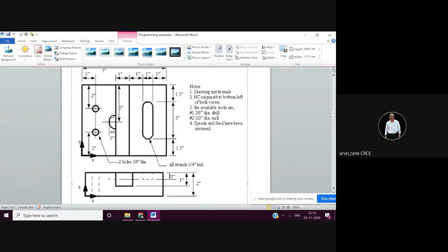So you will have corner, I mean please don't mind, but this is what we have actually seen practically. So here you will have a 1/4 inch radius in the corner, here a 1/4 inch radius in the corner, and in the middle you will get a straight of half inch. So half inch plus 1/4 plus 1/4, that becomes 1 inch.